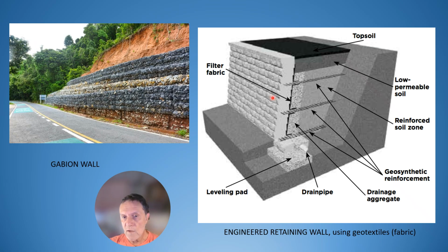So here's another graphic showing what we can do. We can put in a wall here. We can reinforce the soil with what are called geosynthetic sheets, as you see here, here, and here. That strengthens the soil mass behind the restraining wall or retaining wall.